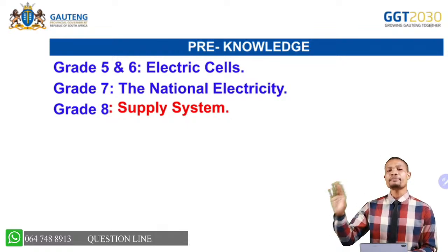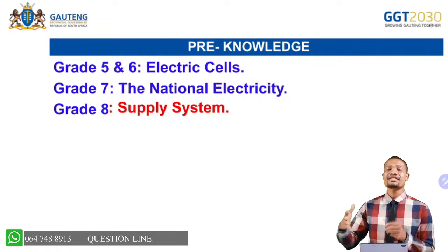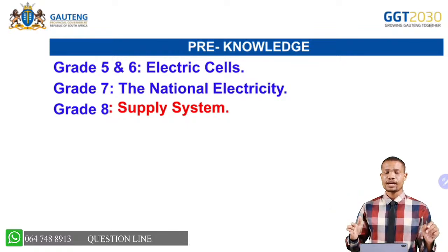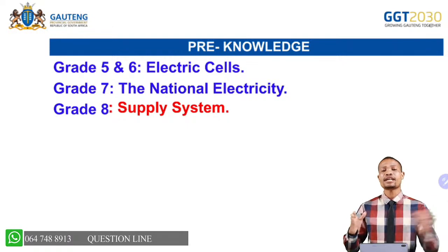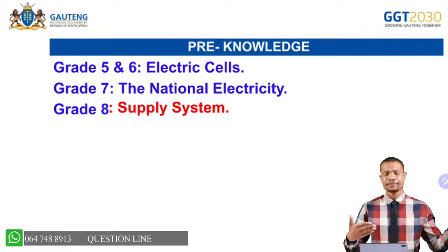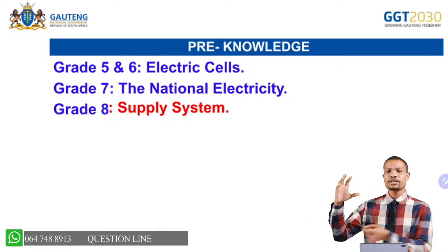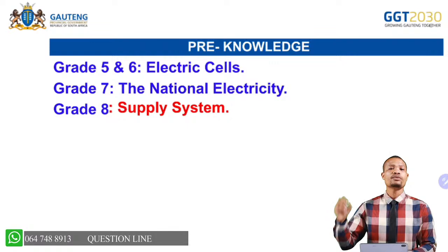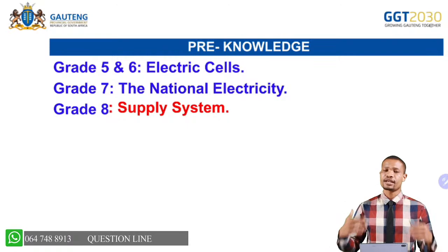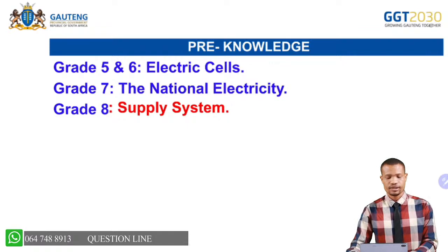Then from there, we step it up through a step-up transformer so that we can compensate for the losses that are going to occur when the electricity is being transported through the power lines. There are energy losses during that because the power lines run through long distances. After that, we put it in a substation, and from there, a step-down transformer. Then we distribute it to our townships or suburbs, and then you are able to draw current from your socket plugs.